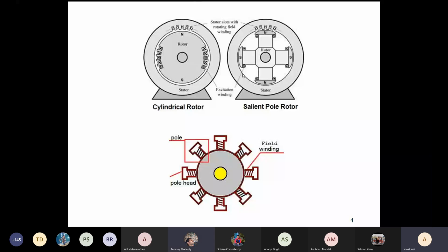To start the machine at the initial point, do we have to use a capacitor as a starter? Not a capacitor. It is basically a DC source that is present there to start this, because just before generating the EMF, you need the field inside. Okay, so that is a separate source.